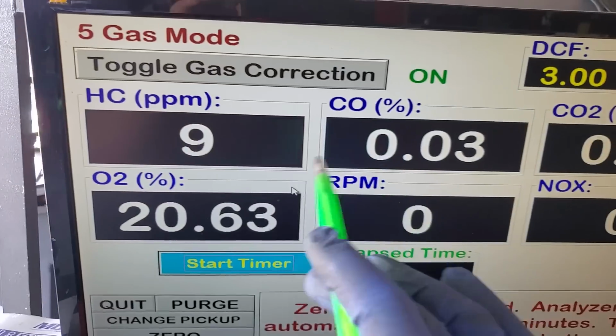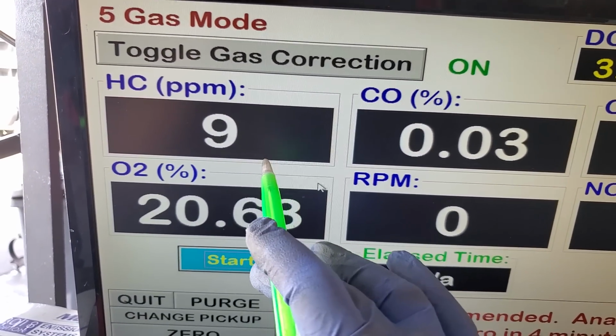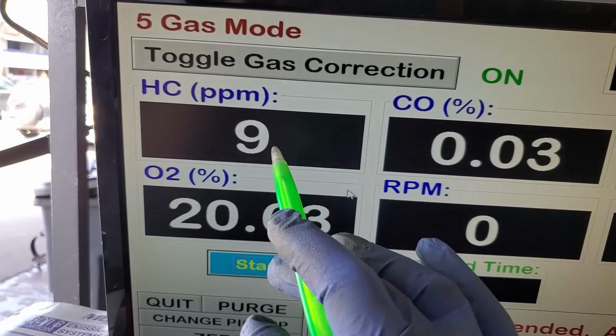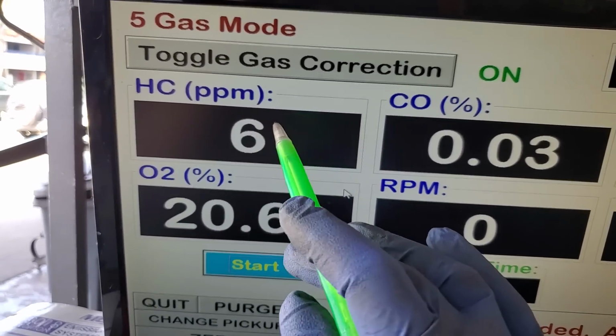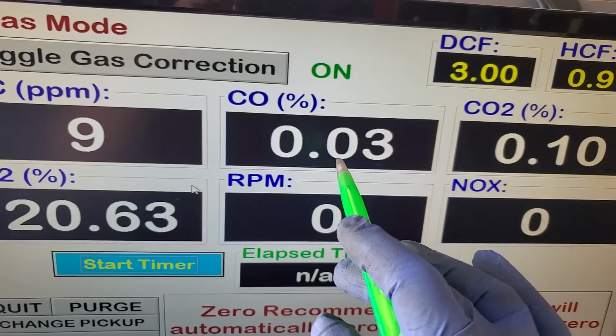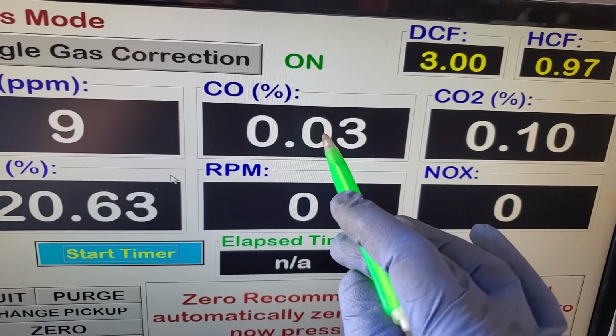But the two classic ones are hydrocarbons, and on an automobile, this is basically raw unburned gasoline. So a misfire, an ignition problem, a mechanical problem is going to cause this to go up. Carbon monoxide is caused by incomplete combustion.